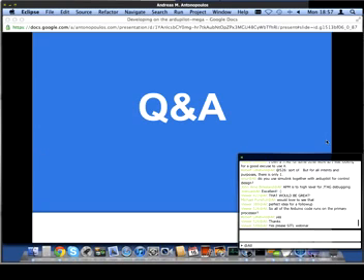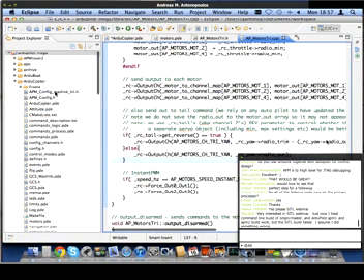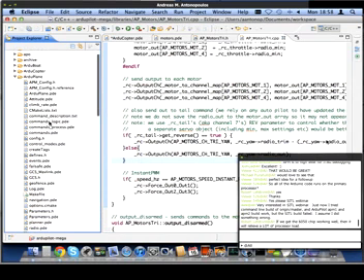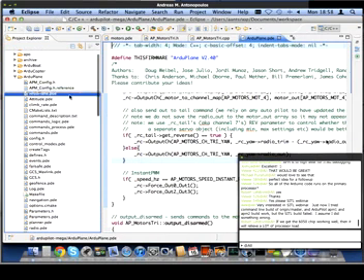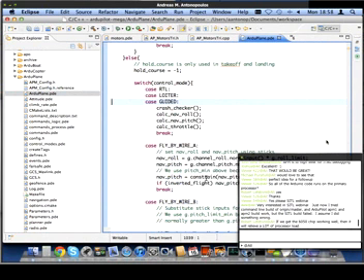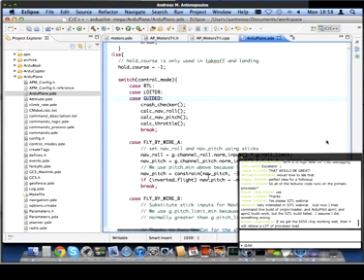Yeah, I have a question. Please. I was looking at the auto land feature that Judge was describing earlier. If you look at the part where, if you don't have airspeed enabled, it sets the nav pitch to a predefined pitch, which is called landing_pitch in this case. That's right. Which file and which line are you looking at so we could actually pull it up? ArduPlane.pde, line 1039.